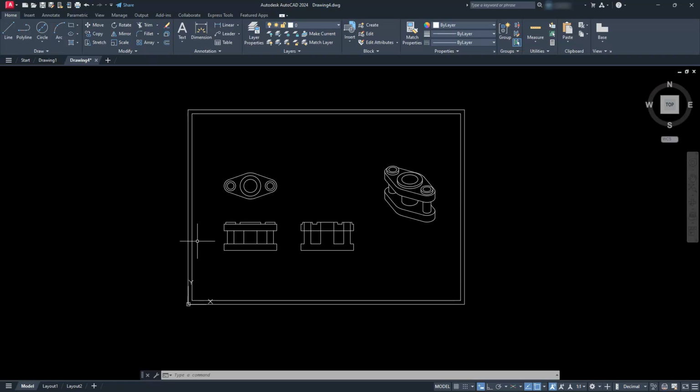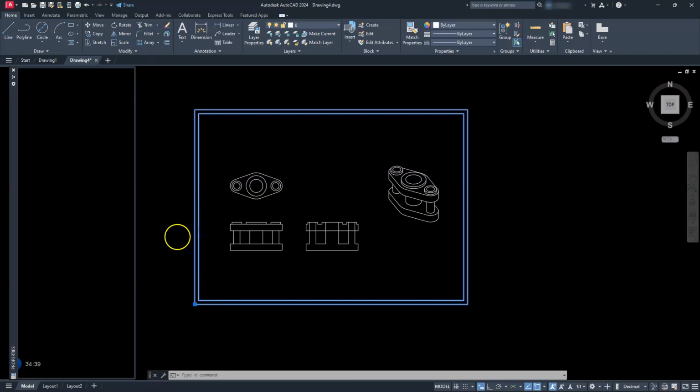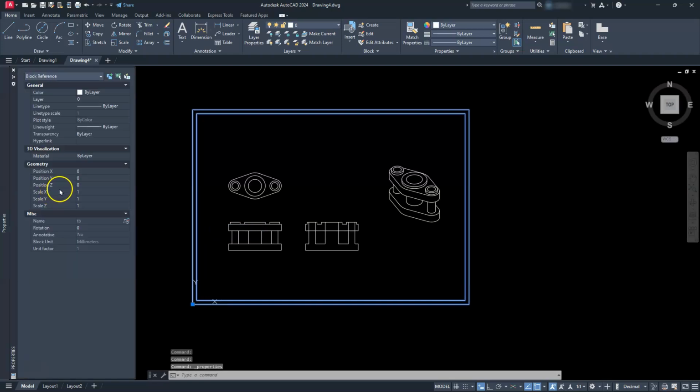We might want to examine if we can make this a little bit smaller or a little bit bigger, depending on how you want to create this drawing. What I mean by that is if I select it here and then I do a right click, and then I bring open my properties window, that's going to open this up. And then I can start playing around with my scale X, scale Y, and scale Z to see if there is something that would fit this, right?